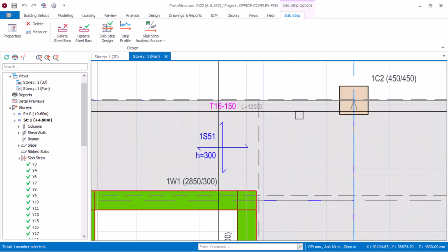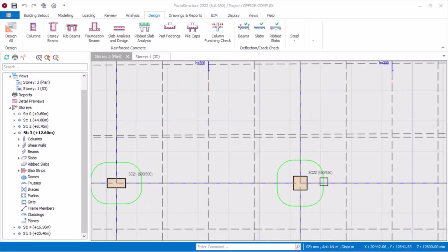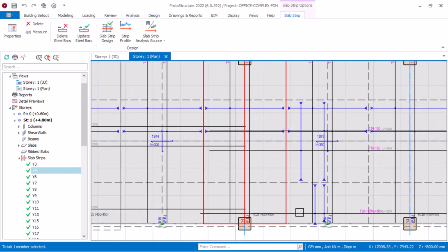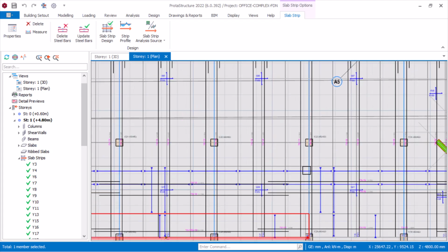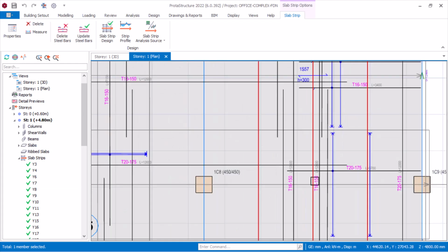Now, when it comes to punching reinforcement, after you have done with the design, let me assume that around each of the columns or some of the columns, you are having a higher value in your area of steel, which will require the punching shear reinforcement after you have done your minimal reinforcement for the slab.